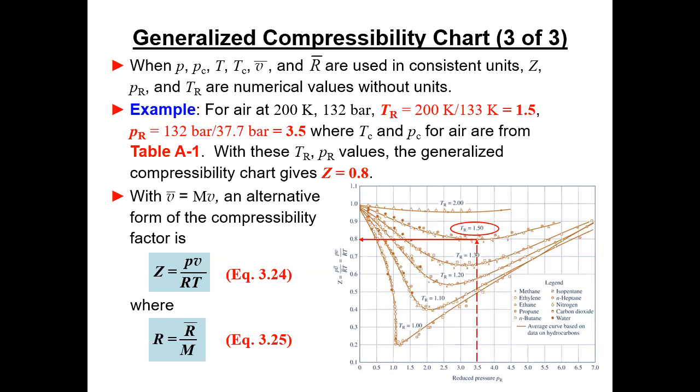And R is called the specific gas constant, which is the universal constant divided by the molecular weight of the gas you're working with. For dry air it's something like 28.965, a weight average. You can do it on a molar basis or a mass basis. If you're doing it on a mass basis, you have to adjust the gas constant with the molecular weight. That makes the units work. Not too bad.